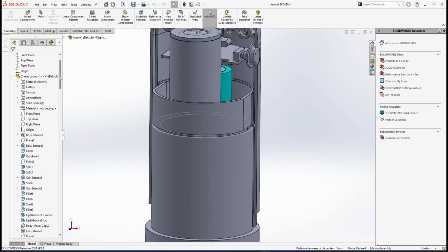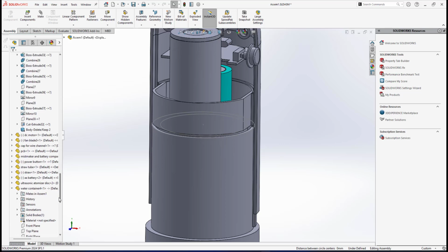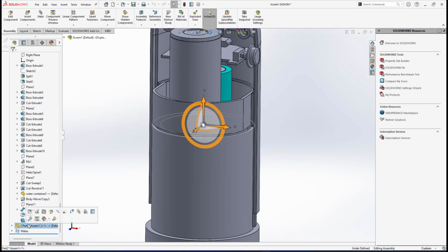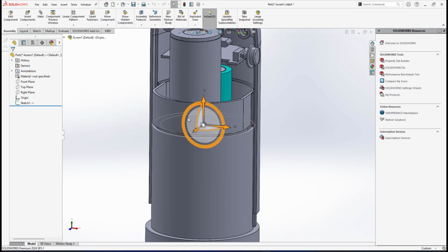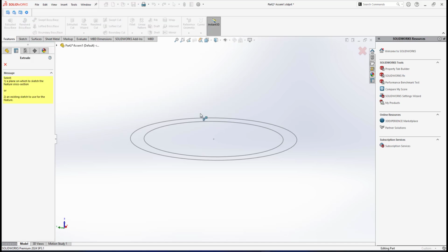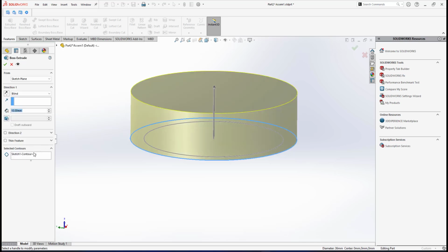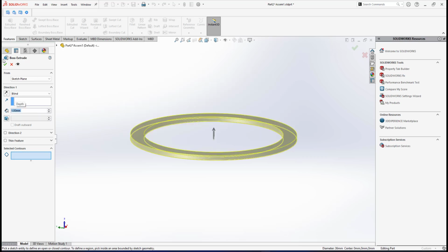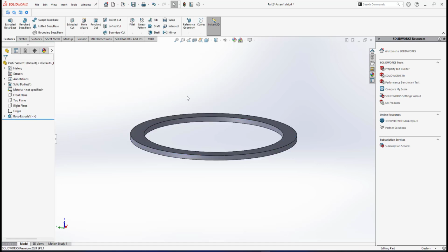As you can see now in this full assembly, if I scroll down here, I have a new part in the assembly. So I will click at this, I will go open part in position. Now I'm in part modeling mode of this new part to create this silicon sealant or rubber sealant. I have the sketch here, so I will do features, extrude. I will select the sketch. Okay, by default it goes to contours, and I'm not using contours. I uncheck the contours, so it goes for the 2 sketches. Then I will go for extrude of 1 millimeter to create the rubber sealant or silicon sealant.